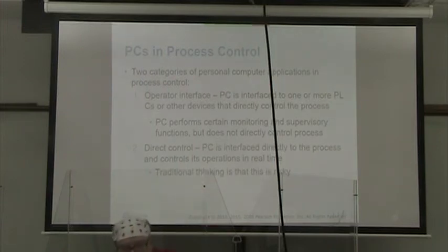So when we use personal computers in process control, first of all, it might be used for an operator interface. Our PC is interfaced to one or more programmable logic controllers or any other devices, and they directly control the process. So our PC then is performing monitoring and supervisory function, but it doesn't directly control the process.